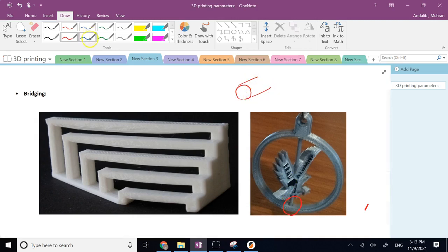That is the bearing hole, and there is this shaft that is inside the bearing hole, like this. There is some small gap between them. Now, as I said, if I don't do bridging, then between the hole and the shaft, the printer would lay plastic and make the connection between them solid, so the shaft cannot rotate inside the bearing.